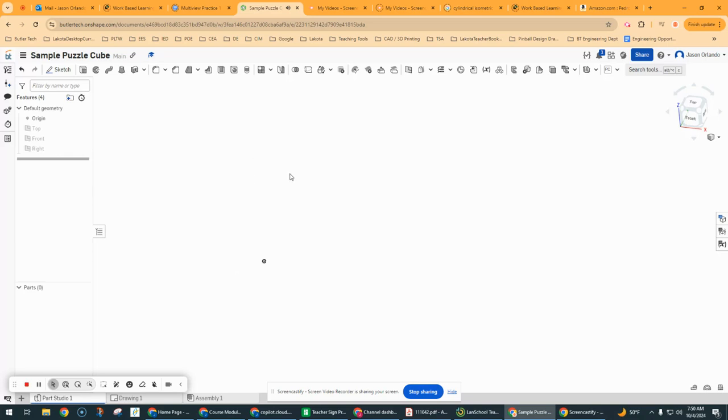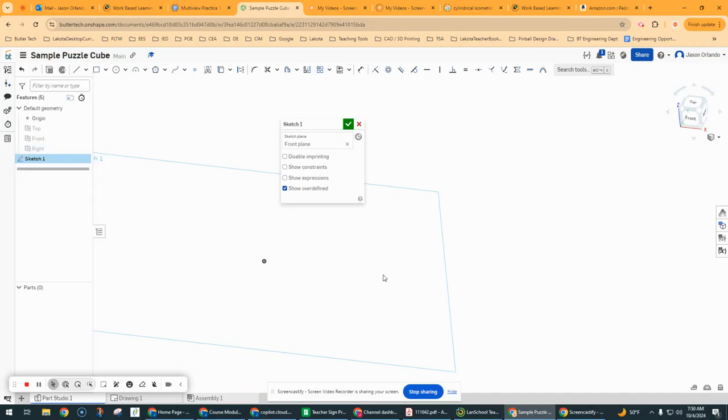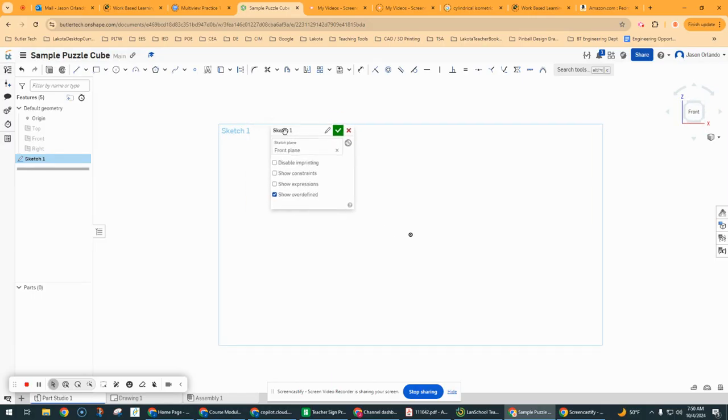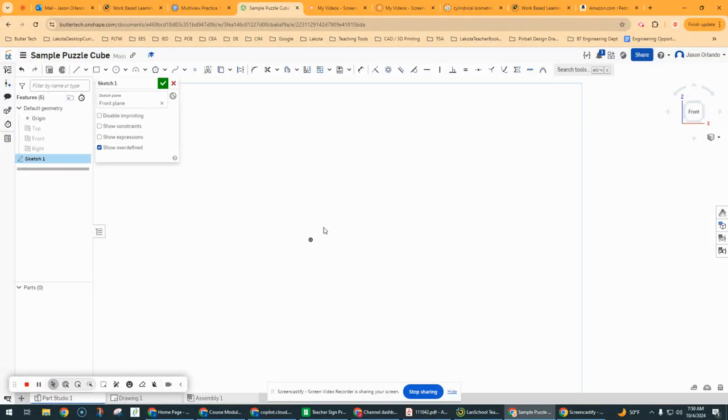All right, we're gonna jump into a sketch and make a solid shape. So sketch, I'm gonna choose the front plane and rotate so that I'm looking straight at the front plane by pressing N on my keyboard or clicking on the front face of the view cube. This dialog box is not in the best location, so I'm gonna scoot it off to the side somewhere, okay?